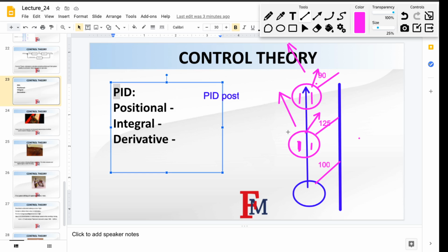So this is considered to be the most trivial, the most naive, only positional PID, right? The decision of what you should do with the speeds of the wheels depends only on your current position and on the ideal position, which is 100. Not on the previous position. So that's considered to be the most naive, and that's why it has a lot of mistakes. The idea is that it can't really adjust to the system.